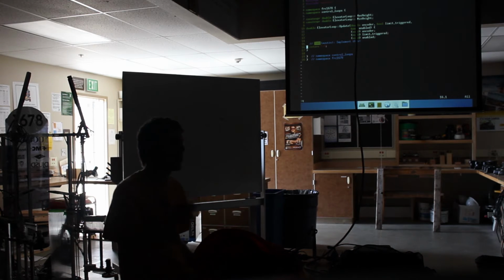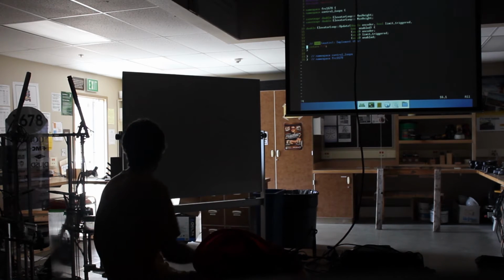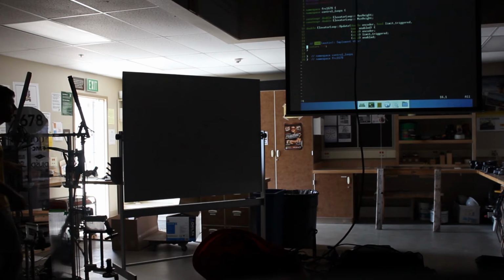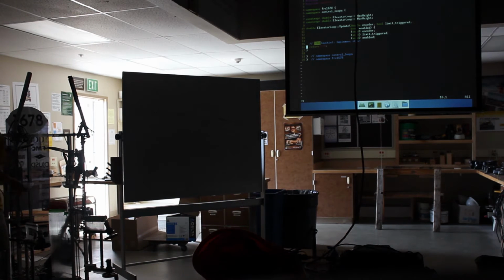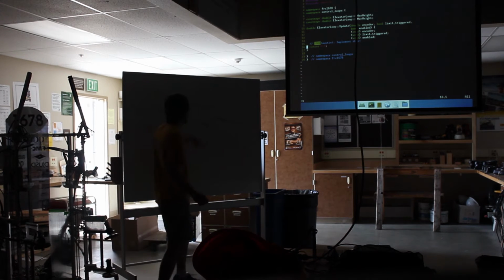No, this is a good question. This is the crux of the problem. So what we do is we only need to do this once, once per startup. So when you turn the robot on, right? So we start out, the elevator's right here, we turned it on. What's the encoder going to read? Zero. But is this zero? No. So what we need to do is figure out the difference between the position that we started at, or the other way I like to say it, what is the offset between what the encoder reads and our absolute coordinates?